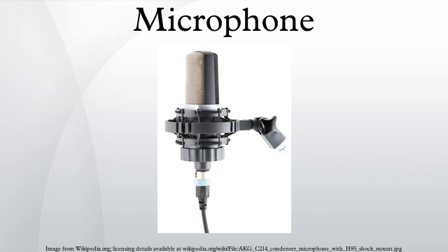Such older ribbon microphones, some of which still provide high-quality sound reproduction, were once valued for this reason, but a good low-frequency response could only be obtained when the ribbon was suspended very loosely, which made them relatively fragile. Modern ribbon materials, including new nanomaterials, have now been introduced that eliminate those concerns, and even improve the effective dynamic range of ribbon microphones at low frequencies.